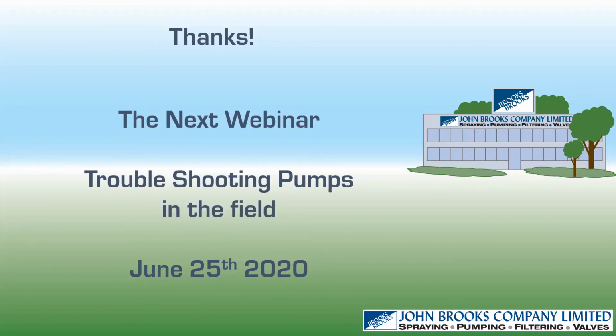We've just got time for one more here. Can a VFD be used to protect the motors where there is a voltage imbalance between phases? It's an interesting one. I have not heard of that being used. I know VFDs, if you mean protected by shutting it off, then yes. The VFD will monitor the 3-phase voltages, and if they become imbalanced, it will shut off the motor. But it cannot fix the problem. I was going to say it can't fix an unbalanced phase, but it could shut down the equipment to protect it. Yes, it would be shutdown protection, not a corrective feature.